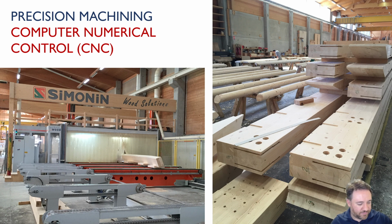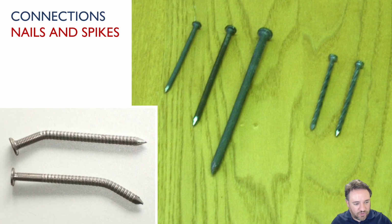So very high precision. Okay, so basically I'm going to go through and talk about all the different types of connections. We're going to start with nails, and I'm going to talk about bolts and all those different things. So, we're probably already familiar with what a nail is and what a nail looks like. But you also probably know that nails are very easy to install. In the limit, you can do it with a hand tool, a hammer. Often in construction, they'll use a pneumatic tool to do the nail installation. But basically, nails fit up through friction. You insert the nail, and the nail pushes aside the wood fibers.